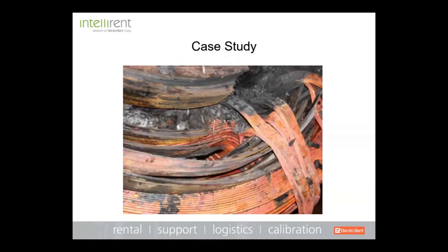If you have a through fault monitor on your system, either in the protective relay or from your monitoring system, and you have no signs of any through faults that exceed that threshold or that the relay has recorded, I would probably tell you that leakage reactance or SFRA would not be a necessary test when you go out to do your routine testing.